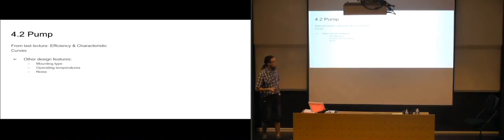If you're going to place this in the same room where people are going to work, it is nice to keep the noise level fairly low, preferably, if you can, beneath 85 decibels, because in a work situation, at least here in Norway, the law says that if you have it above 85 decibels in noise level, constant in your work environment, you're supposed to have protection for your ears.